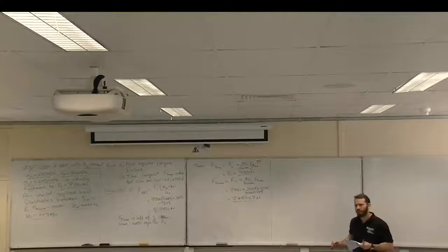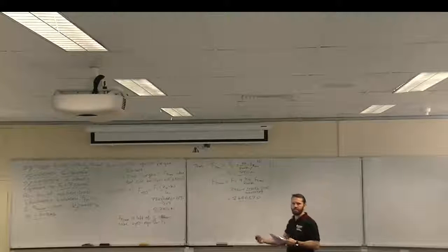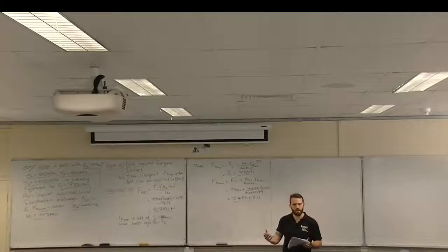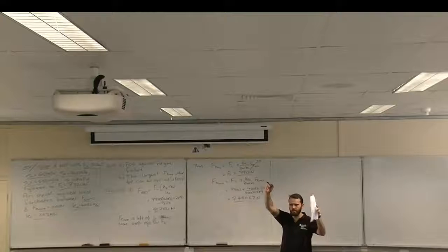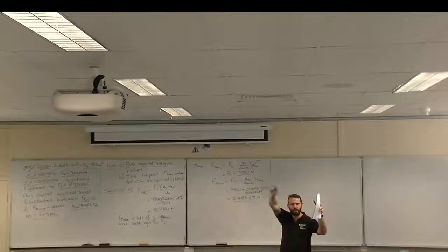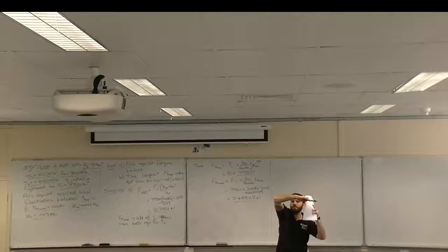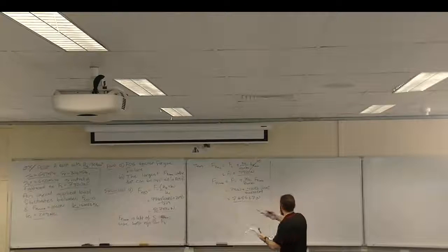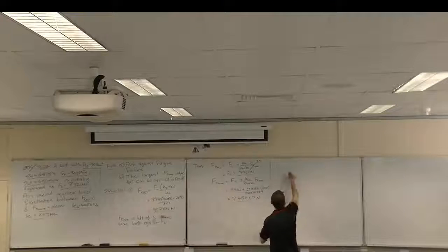And so an additional advantage to having that pretension is because of the change in fluctuation, particularly in between the 0 point and the separation point, because of the change in angle of that line, the decrease in slope of that line means that large changes in FE actually result in smaller changes in FB. I wonder whether I need to draw that to explain it a better way.